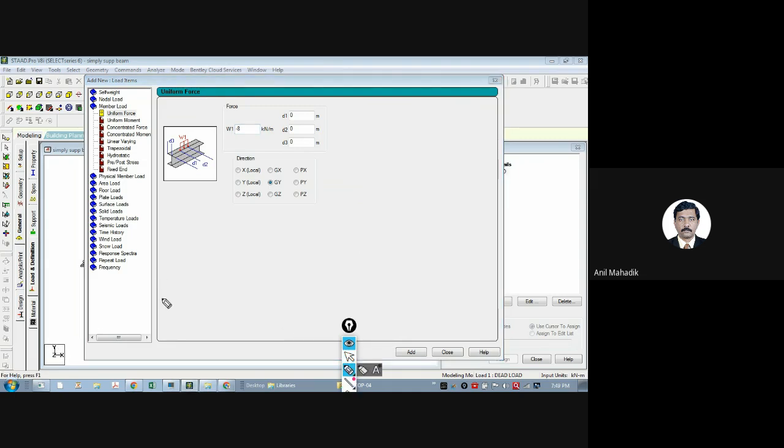here, our coordinate axis is like this. ये हमारा y upper है और ये मेरा x है. And you know that our beam is drawn like this. Correct? ये हमारा beam है ना. और what is the direction of loading? Downward. So my W 8 kilonewton per meter is downward, and your y-axis is upward. And here you can see it is written as GY. That means load is downward and axis is upward. That's why I am putting -8 over here.